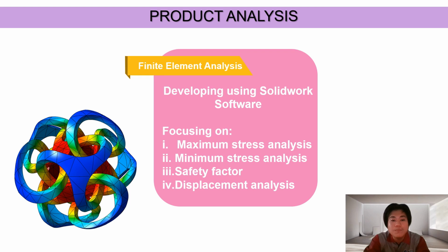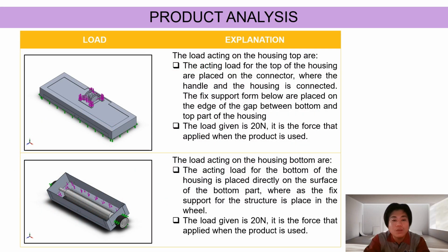Next, the purpose of the product analysis developed with SolidWorks software is to determine the stress, displacement, and safety factors. When a force of 20 Newton is applied to both components, the load acting on the housing top is placed on the connector which connects the handle and the housing.